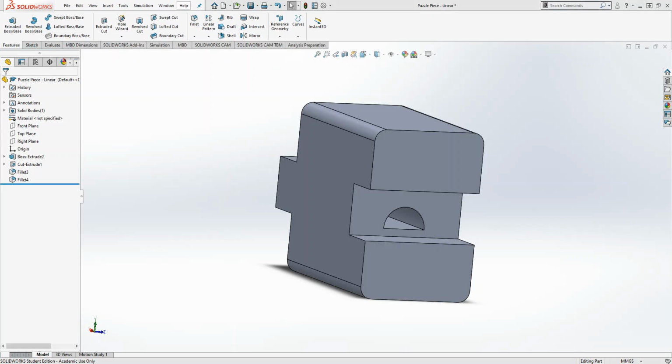Right? Try it again, and oh, look at that. I've actually started to curve out my parts. Right? So you could do the same thing where you select multiple different edges using Shift, however you want to select all these corners, select the fillet tool, and I could just fillet all the different things at once. Look at that. Now we have parts with rounded and softer edges, which is a great thing if you want to design a part that you didn't want to cut someone, for example. Sharp edges can be dangerous, so maybe we wanted to make a part that's rounded out.